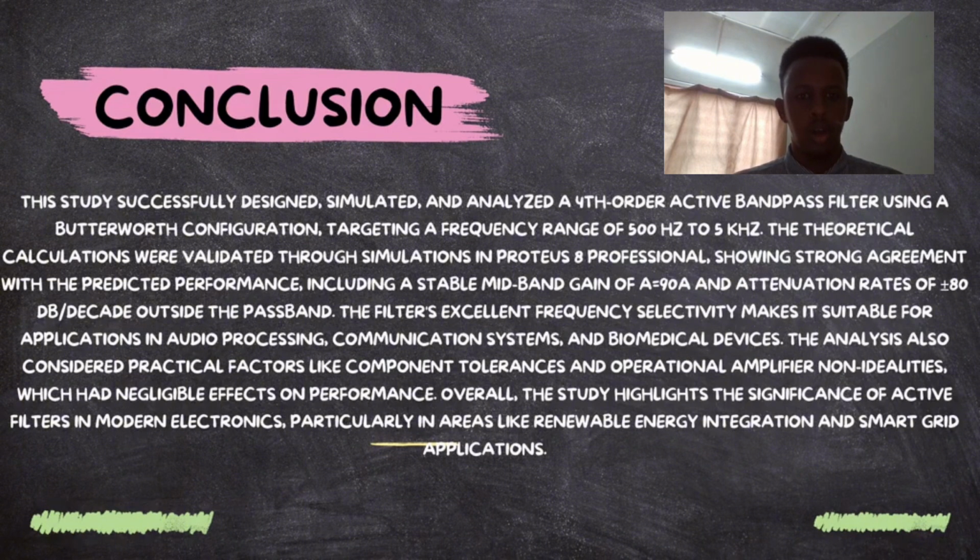Conclusion: the study successfully designed, simulated, and analyzed a fourth-order active bandpass filter using a Butterworth configuration targeting a frequency range of 500 Hz to 5 kHz.